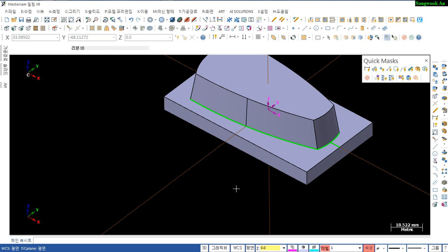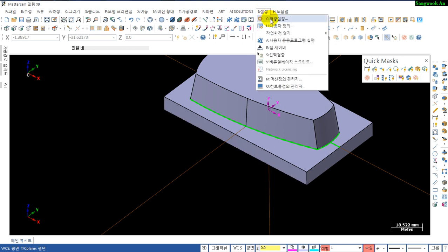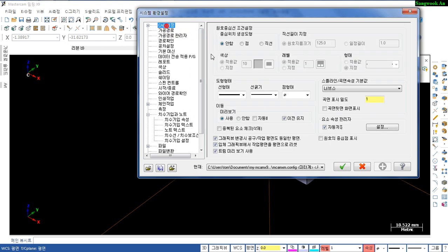And the front plane. So as I talk to you, please check this option. And the graphic view is aligned with construction view. So if you change the graphic view, automatically construction plane changed according to the graphic view. So when you do a modeling, it is very good option. But when you make a toolpath, please make it off. Okay, and so even though in Korean, so I'm pretty sure you can understand.